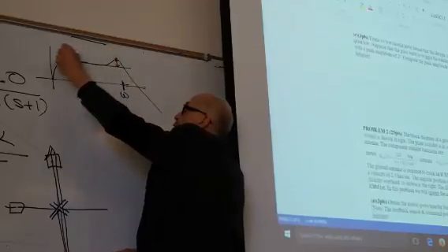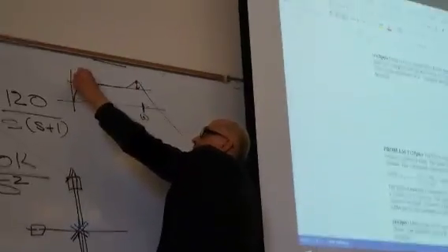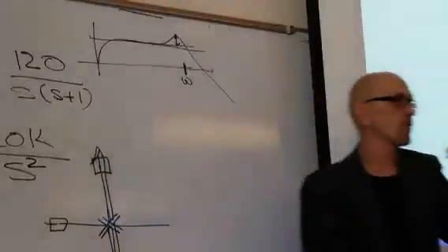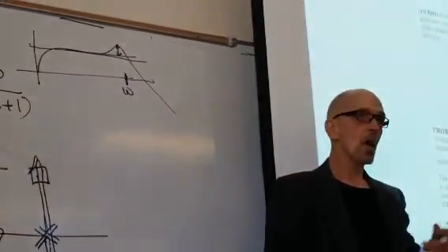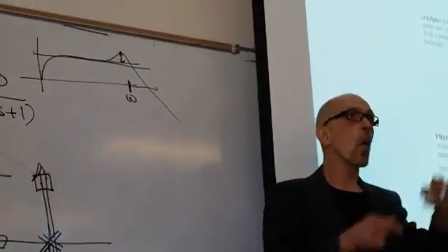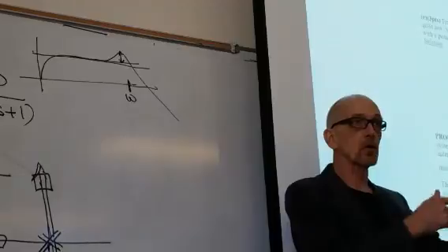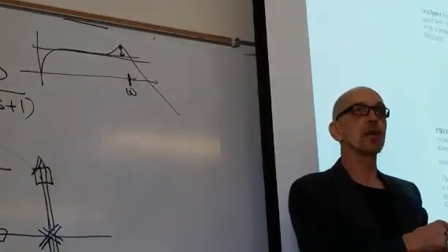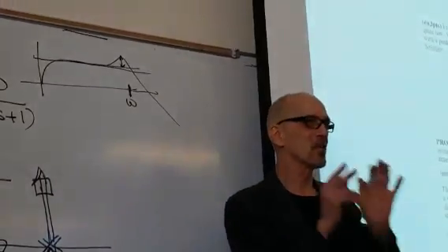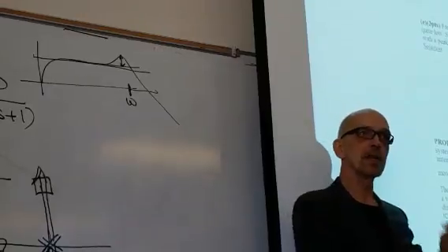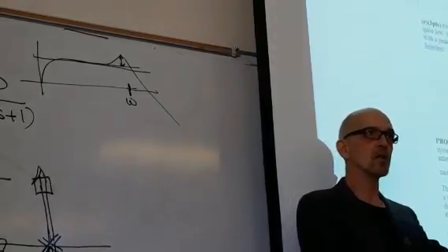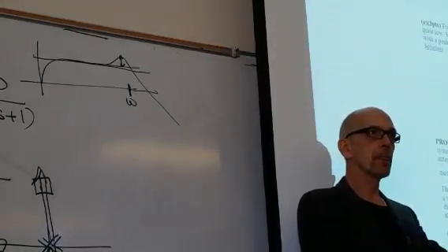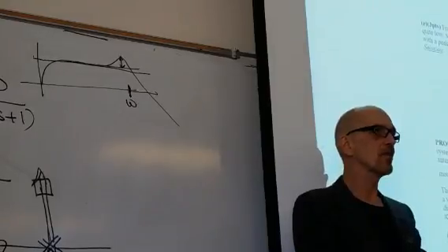Remember, with sensors, ideally, you want a flat FRF. That way, all acceleration is all voltage. So many volts per G. Which frequency? No, all frequencies. Just volts per G. That's what you want for a sensor, right? But not every sensor has a flat FRF.